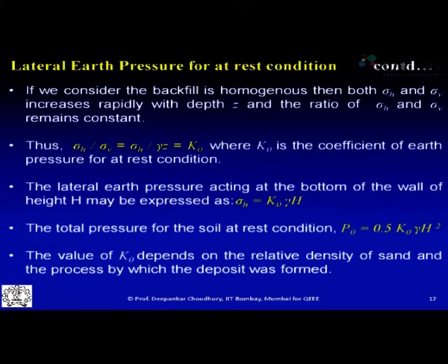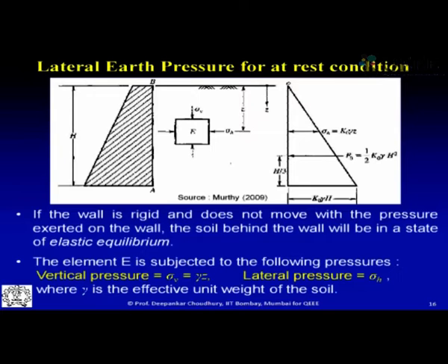So the value of this K0 depends on the relative density of the sand and the process by which that deposit got formed. So we will see that K0 value and its various definitions and equations as far as the elastic equilibrium is concerned. So we were discussing the coefficient of earth pressure at rest condition K0, and we have already seen that this is at the state of elastic equilibrium.